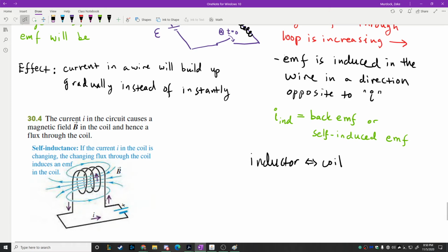The idea is that the current flowing here produces a magnetic field. And in a way, as the current's flowing, it has to kind of build that magnetic field up. And it doesn't happen instantly. It starts off and it's kind of gradually building up current. And then, once the current's established, you've got a magnetic field. The really cool thing, too, is that when you try to cut the current off, that magnetic field contains energy in it, and it doesn't just instantly disappear. So the magnetic field can actually become a source for a current flowing in the opposite direction as it tries to decay.